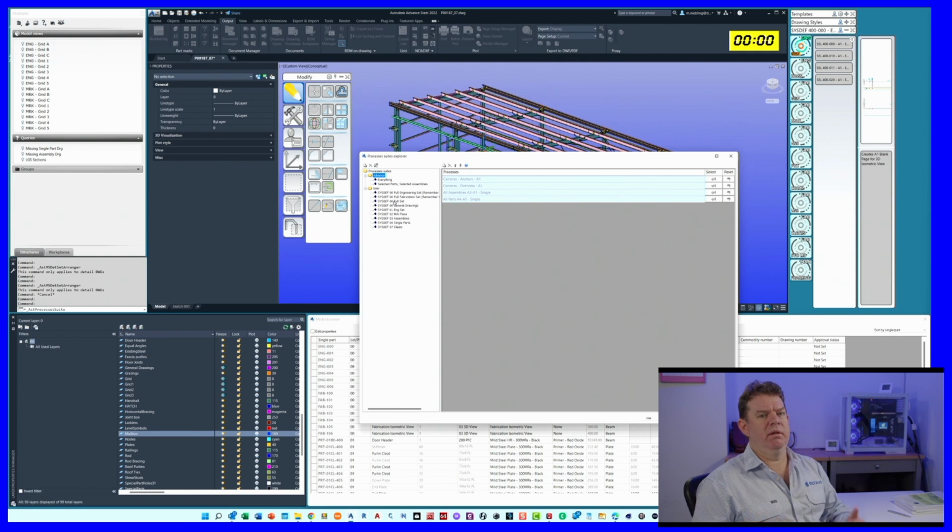If I wanted to run both the engineering and the fabrication set all the way through, I can do that basically as a preliminary check to see if all my model rules and everything is working nicely. I can delete that set and then come back and make this change where we use the 100 series for our engineering drawings, and then the 200 series for our fabrication.